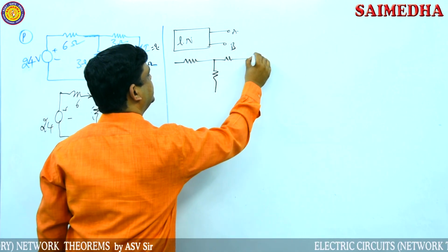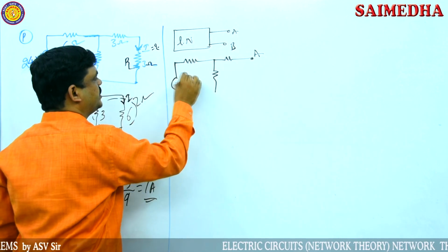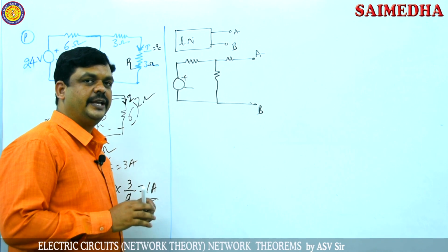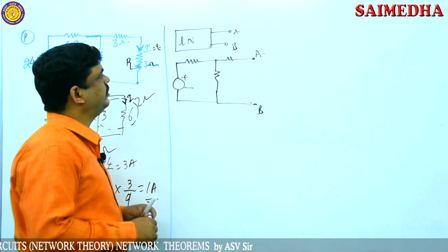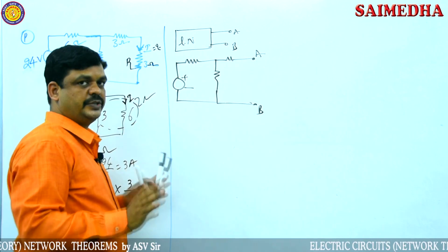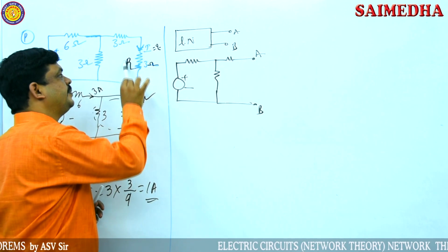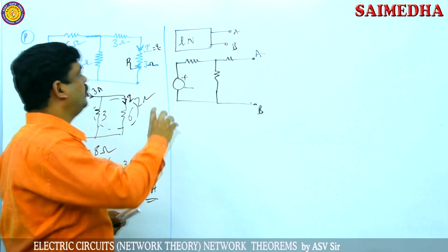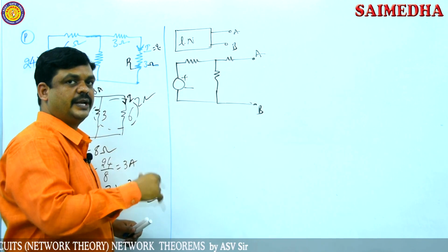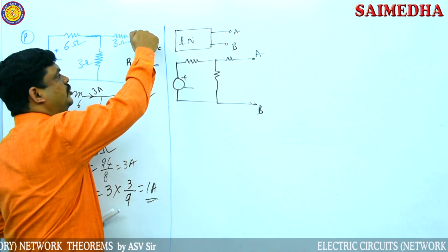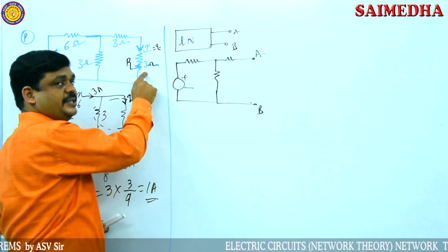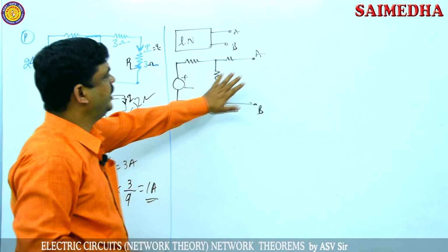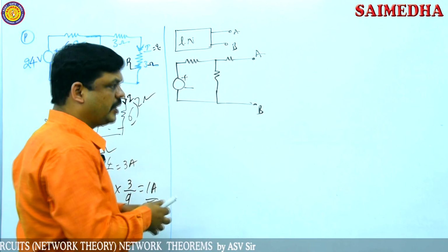Now the circuit is like this. So the voltage source is connected as it is. Thevenin's theorem requires a linear network connected in between open circuit load terminals. So this network is required. That's why the first step we have to apply this procedure: open the load resistance, open the load terminals. To open the load terminals, the load resistor is eliminated, because according to the given question, find the current through the 3 ohms resistor. So now this resistor acts as a load. So the load is eliminated. Now the circuit acts as open circuit load terminals.